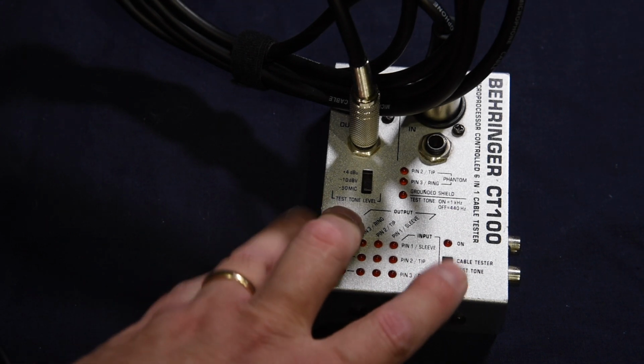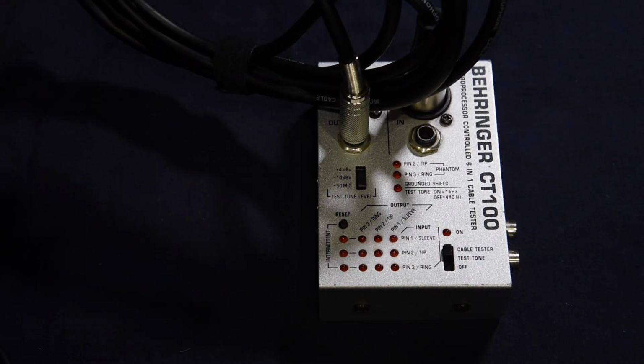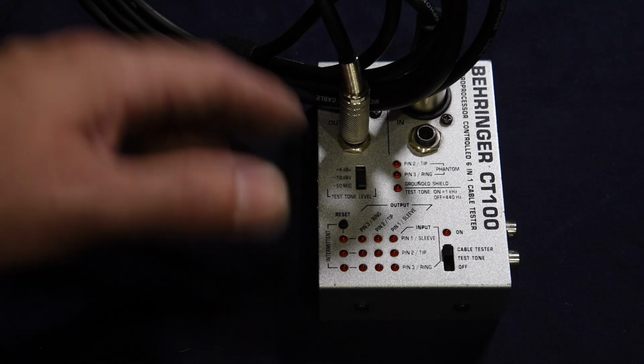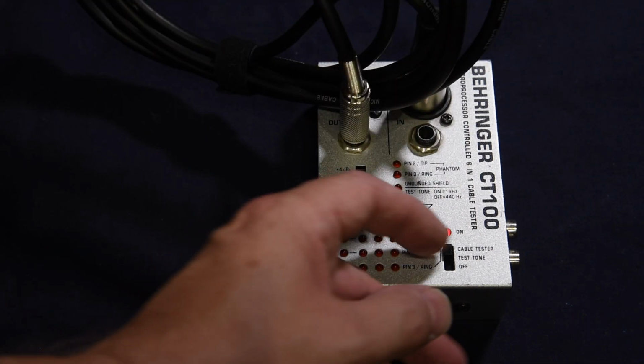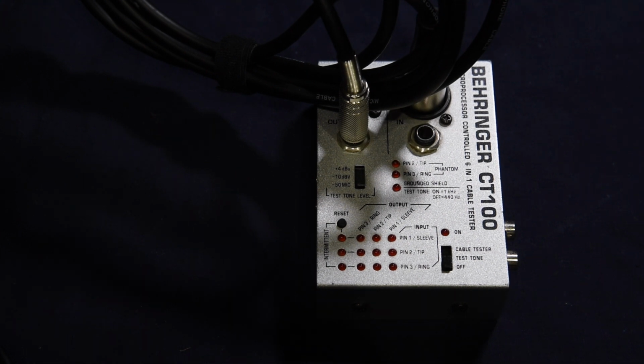You can also use it in installed cable mode. So here you turn it on by holding down the reset button, and therefore if you had an installed cable, like a cable from front to back, if you put a short at the other end, you can see those shorts in there. So that's what the cable tester does.